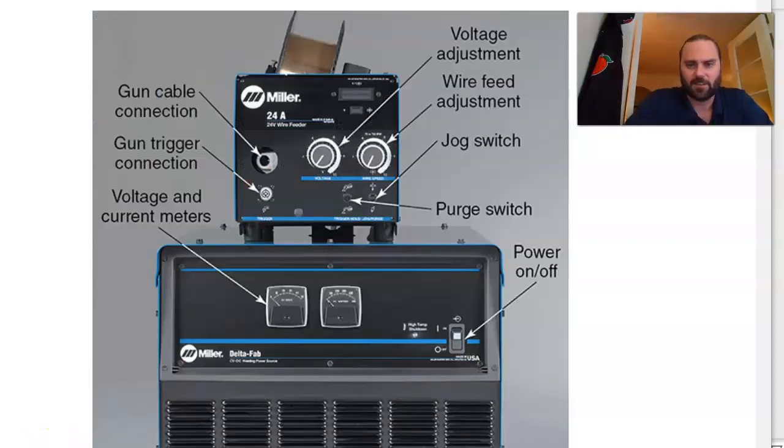Here's a look at a welding machine. We'll go over each part. It's similar to what we have with our XMTs. Our XMTs are a little bit smaller with the power supplies, but the wire feed is similar. Obviously, we have our reel. Our drive rolls are internally inside our wire feeder. This is where we would hook up our gun. This is the trigger for the gun that's going to move your drive rolls. This is actually going to have our gas hose and hookup for our gun.